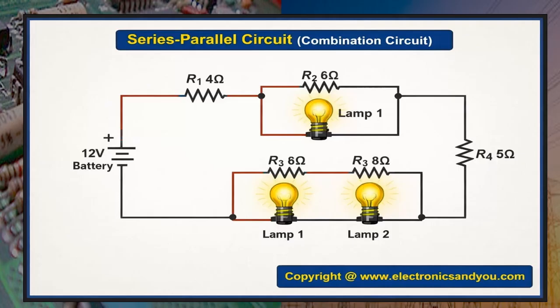But later when you look at circuit analysis, how to combine resistors in series and parallel, you will see how we can reduce this whole circuit into one resistor, so we can find out the total current, the voltage, power, energy, and all these things. But the basic concept now is, the series circuit, one path, parallel circuit, multiple branches. Series circuit, when one component goes off or the circuit breaks, everything stops. While for parallel, if one branch is open or faulty, the other branch is still working. Current is constant in a series circuit, voltage is constant in a parallel circuit.